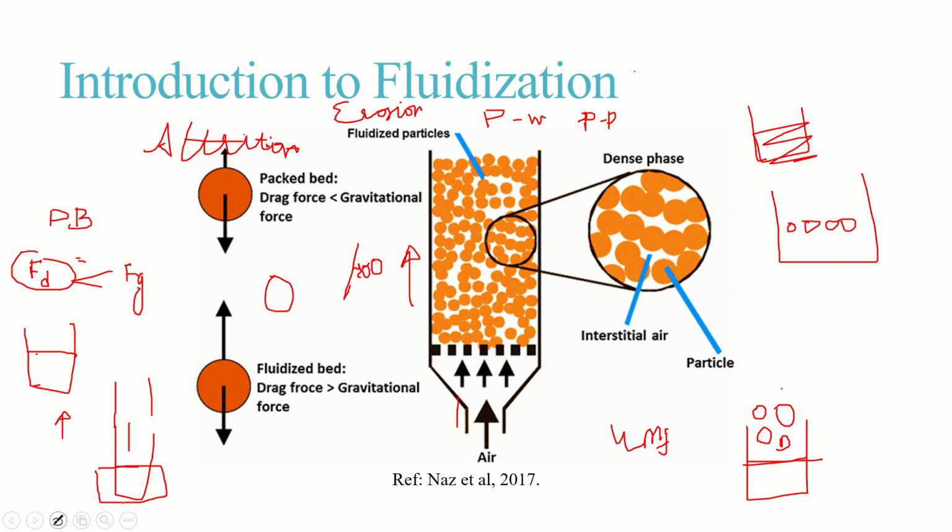But when we are dealing with the fluidized bed, since air is passing over here, depending on the velocity, the particles can be easily moved over, collected and regenerated, and passed back over here. This is the principle used in FCC, fluid catalytic cracking. All these things are made possible only when we are dealing with the fluidized bed.